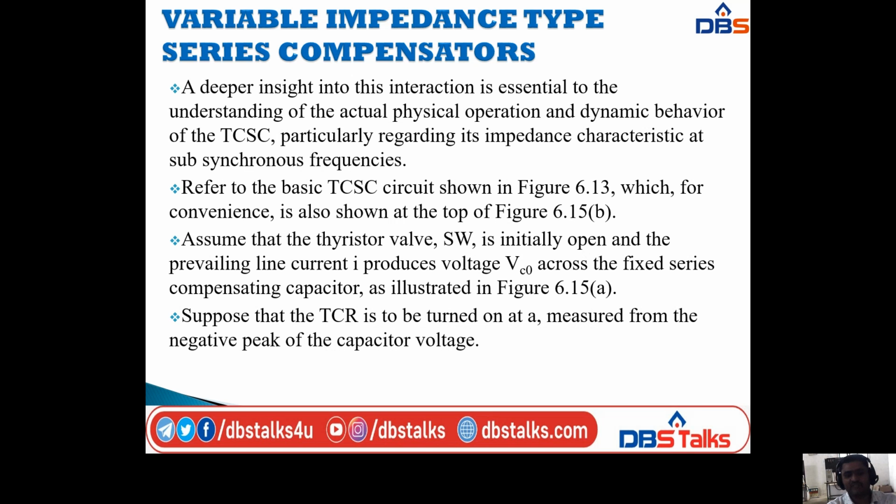So refer to the basic TCSC circuit shown in the previous slides, also shown at the top of the figure for convenience. But assume that the thyristor valve, that is the switch, is initially open and the freewheeling line current I produces voltage VC naught across the fixed series compensating capacitor, as illustrated in the A diagram.